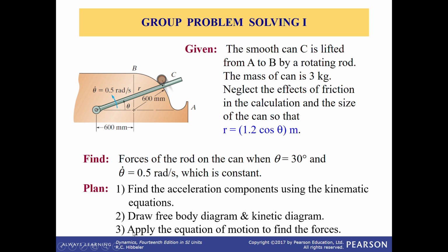And the last one is to apply the equation of motion to find the forces. So just remember these three steps. Draw the free body diagram, draw the kinetic diagram, and then find the acceleration components, in this case a theta and a_r. And later you need to refer back to your free body diagram and kinetic diagram to apply the equation of motion.